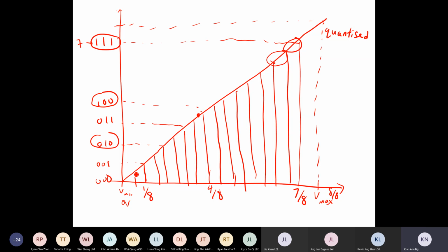As you have more and more bits, say 12 bits, you can quantize even more. It's very hard to draw. Not 6 bits, sorry, this was just 3 bits. So 4 bits, 5 bits. If the number of bits increases, you can quantize smaller and smaller voltage ranges. This is called resolution.